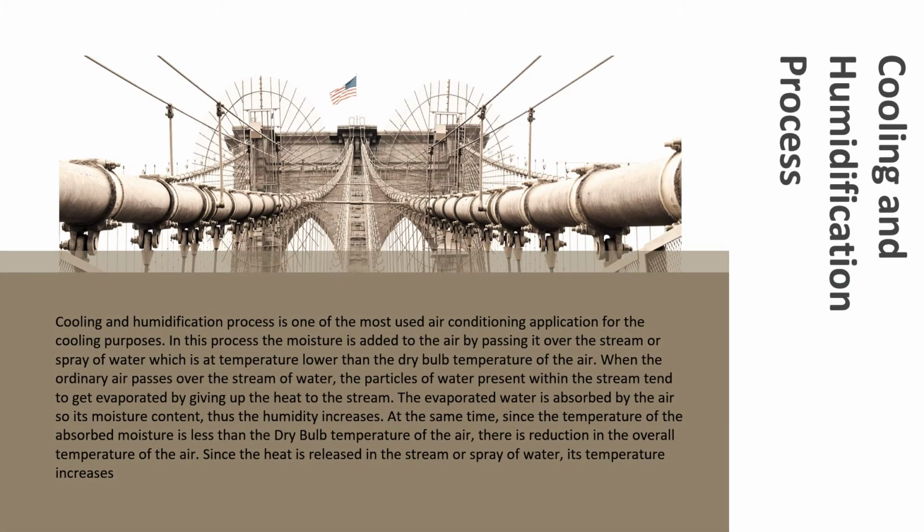Since the main purpose of this video is to introduce you to cooling towers, we must first know the cooling and humidification process. Cooling and humidification is one of the most used air conditioning applications for cooling purposes. In this process, moisture is added to the air by passing it over a stream or spray of water, which is at a temperature lower than the dry bulb temperature of the air.